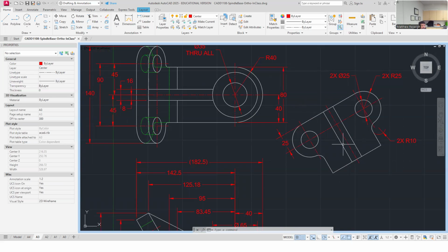Then your auxiliary view is, yeah. I think what I'm doing is I'm going to put dimensions over on my auxiliary view if I feel like I've saturated my other two views, and that's my only reason. I'm definitely reserving my auxiliary view for what is truly needing to be dimensioned over there, which is that radius in that hole specifically, and the two little radiuses in that hole. So I'm definitely restricting myself to just what has to go over there, and then I'll push stuff over there if I just don't have room for it on my other views. So that's my thought process a little bit.